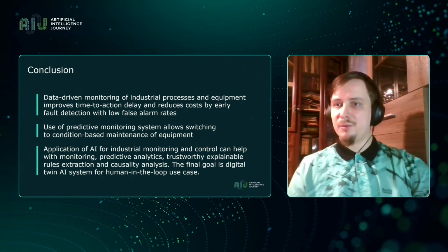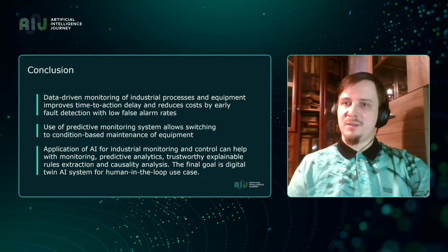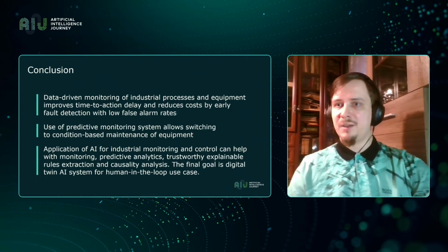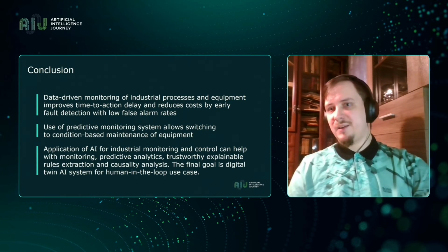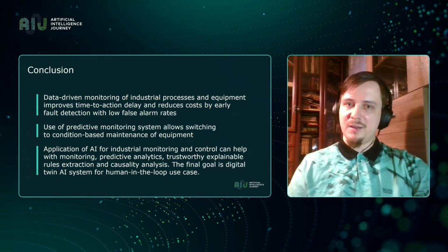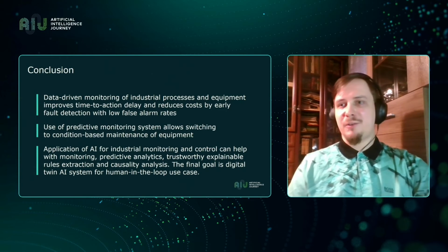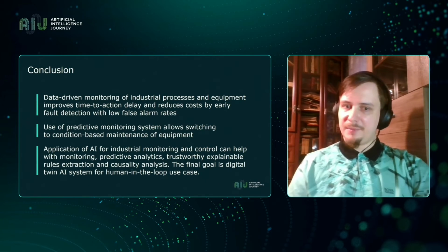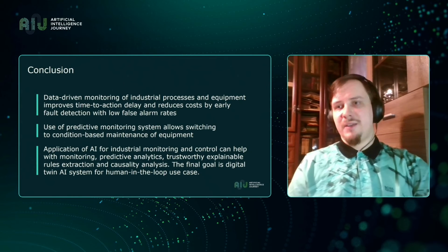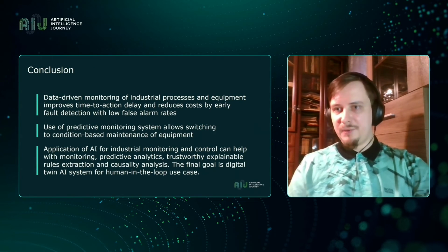And you can write requests to data, and it can be simple in terms of time. For instance, in case the temperature is rising within a certain time, or in case the pressure goes up within a certain time, and after that, the rotation of the engine is accelerating. This is a signal, this is a red flag that notifies us that the situation is pre-emergency. And it will help people make decisions based on data, and it will help detect causality.